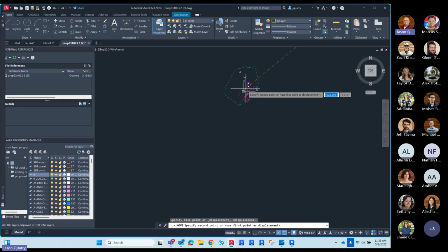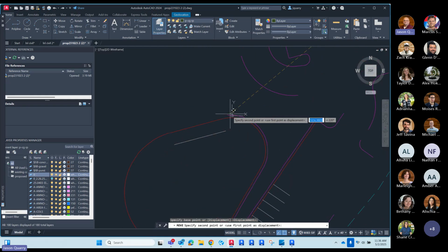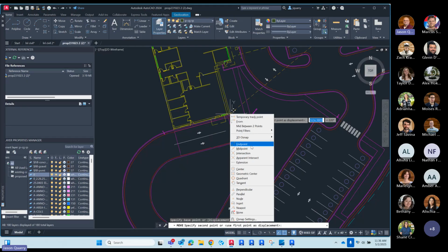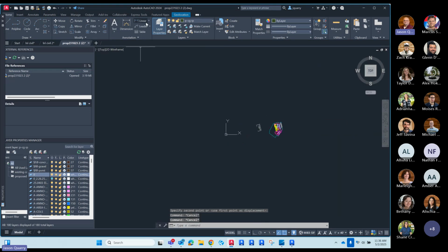I'm going to place this directly on this UCS, but you can notice that there's really no snaps. I think sometimes some people have tried Node. I think Point is another one, but I don't even see Point in here. Yeah. So I'll give you a little secret. What I do is I'll just move this out in space and I'll just create a line real quick.